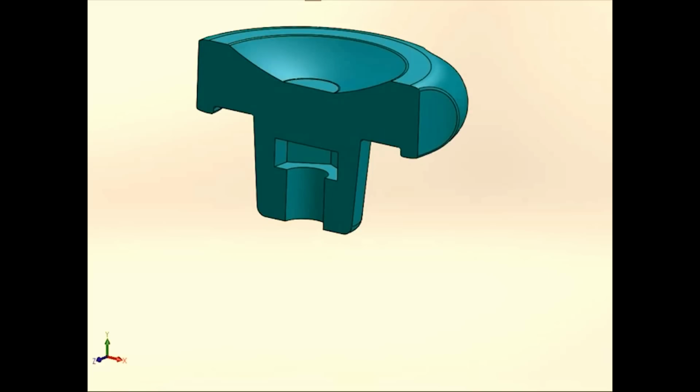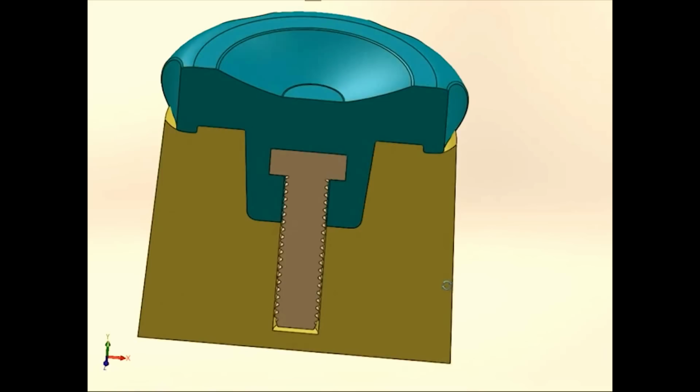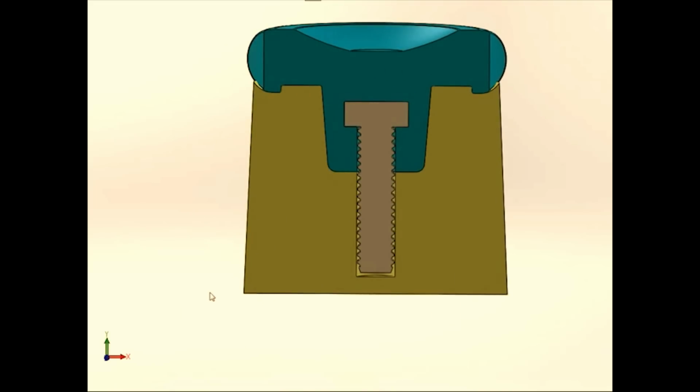So it's going to look something like this. Once we have the support, I drew this in so you can kind of get an idea. The yellow is the support material, and we're going to put a hole inside the support. We're also going to add all the support in there so that we would get something like that to accept the screw. So it's an additive process, so it starts from the bottom of your model and goes up.